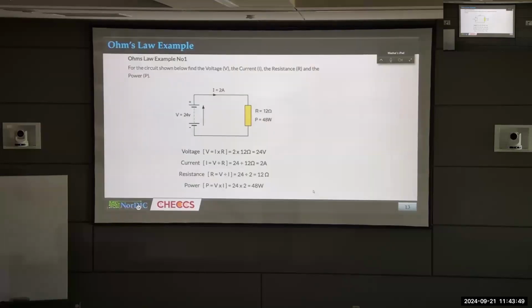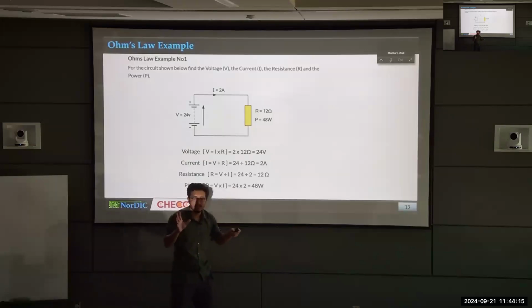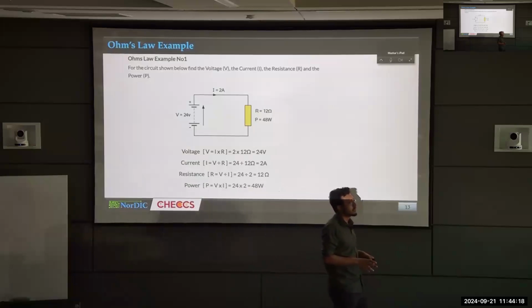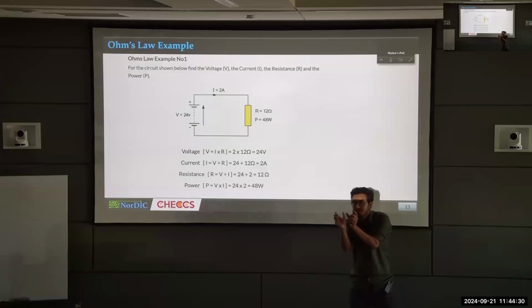This is what, so there was one slide which I will explain later on. This is a very basic circuit, and here what we have done is we have connected a battery, not a battery actually, several batteries, okay? A series of batteries, as I have already discussed, to increase the voltage. So for example, you need a 24-volt battery, but you go to the market and you see that there is no 24-volt battery, but you have, let's say, a 6-volt battery. So what you can do, you can just buy 4 of them and connect one after another.